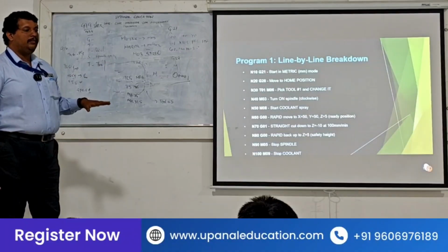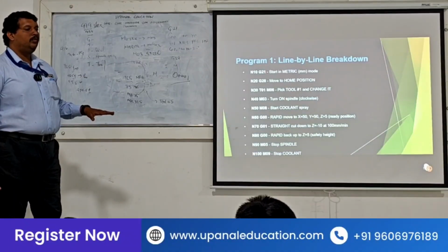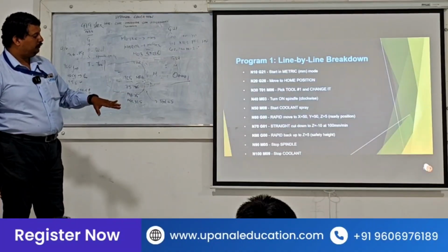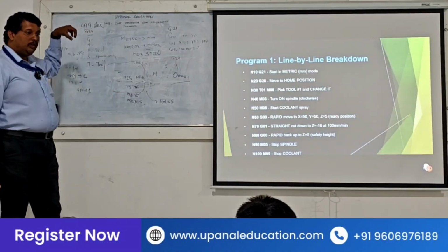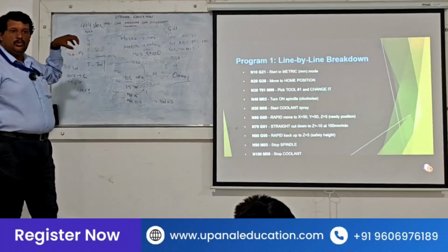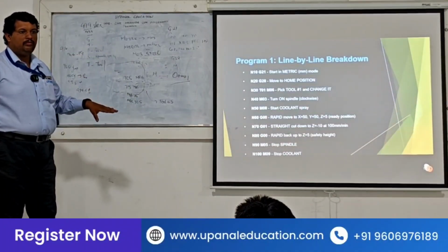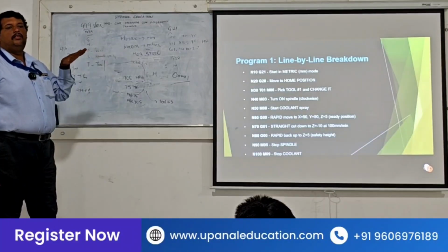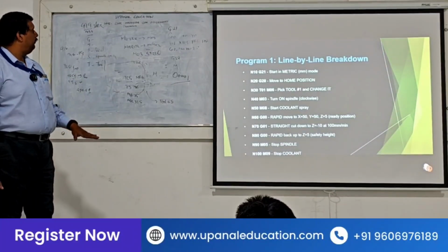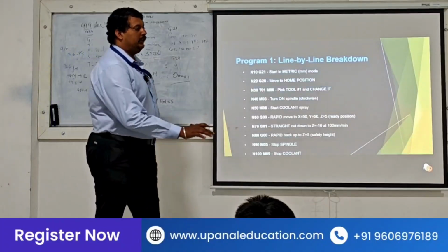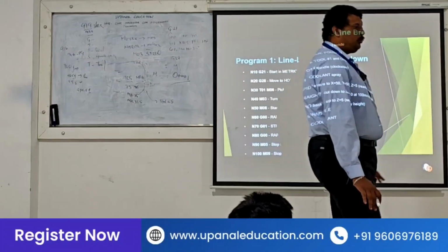Once that is over, what will we do? We will first go to home position, then spindle off, then the coolant will be off, and we will end the program by giving M30. I'll show you a CNC program, a G code M code program, now.